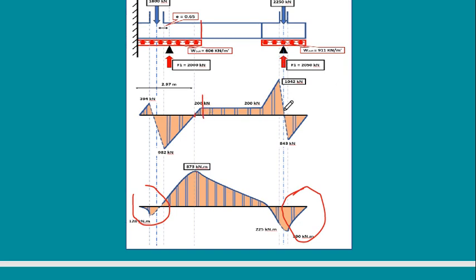So from this location to this location, I don't have additional loads. So the shearing force diagram will continue as it is, then it will reach the soil again, the soil starts to push, then it will reach the other column, and then I reach the soil. How to check that I'm correct? By calculation, this point would be zero, because this is a stable structure. The value of the shearing force coming from above is equal to the value of the shearing force coming from below. If they are not equal, it means that my footing is either going up or going down.